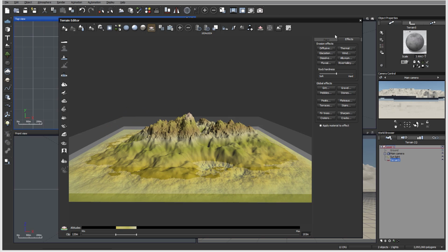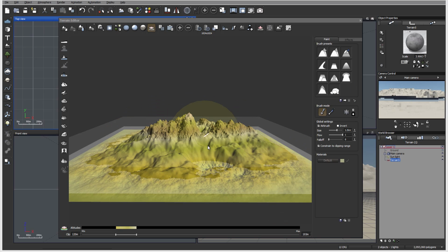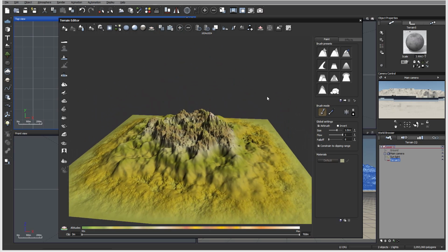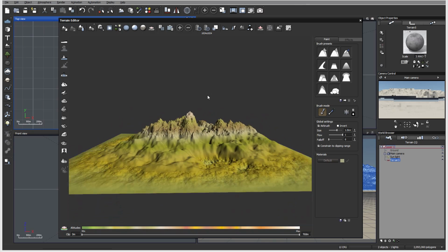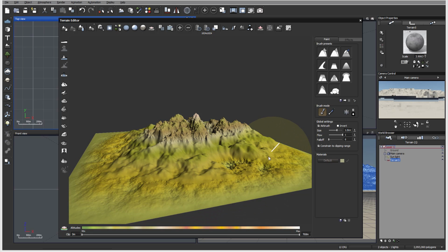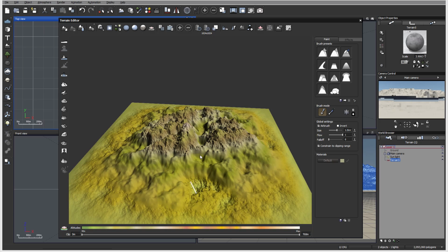But be sure you deselect or remove it before you close the editors, because like right here in the preview, you can see the clipping area actually applies in our render to cut off that terrain. So when I'm done, I want to remove my clipping area, which will recreate the full terrain that I want to use. And we can uncheck showing clipping areas this time. So it does help. And also the clipping area may help you to mold it. For example, if I don't want to touch lower areas, I can set a clipping area and just work with the brush preset tools on a specific area that I want to be affected.